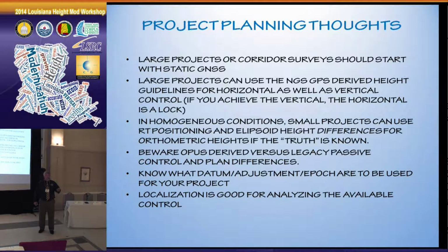I was talking with Dave Newcomer at the break. In Florida, their DOT uses a certain epoch, right off the data sheet for their information, and they're using current positions as if they're published positions, which isn't true, which means the error gets shifted into the atmospheric modeling. So just to say, it behooves us to know what we're using as truth.